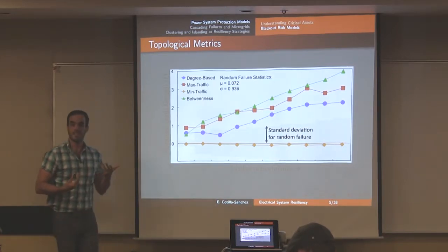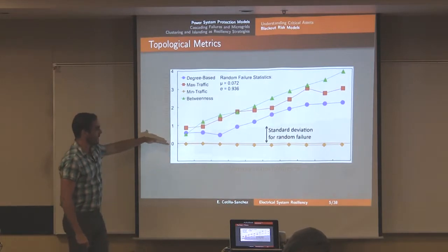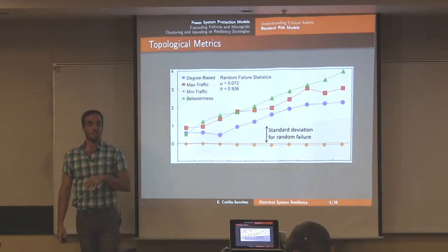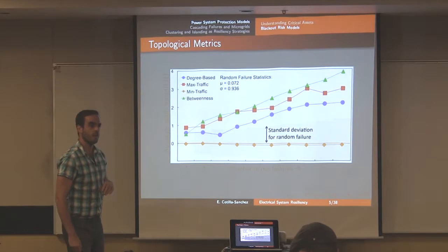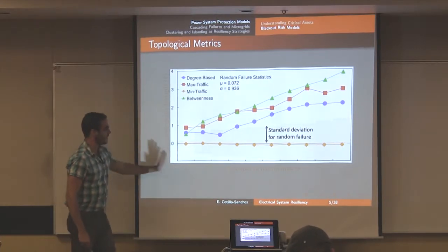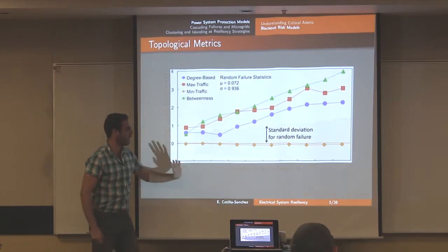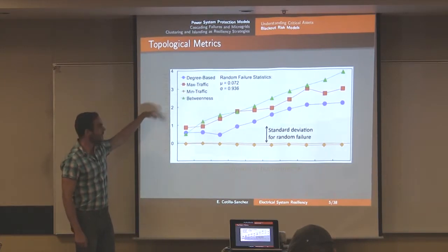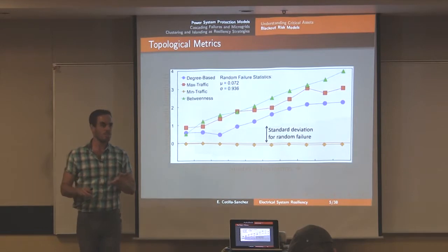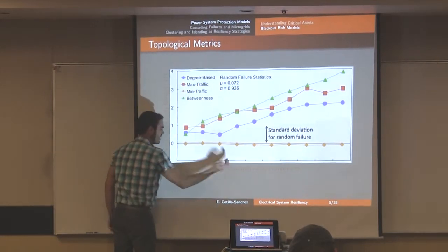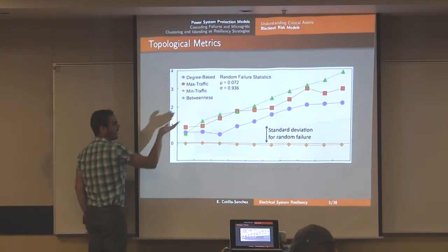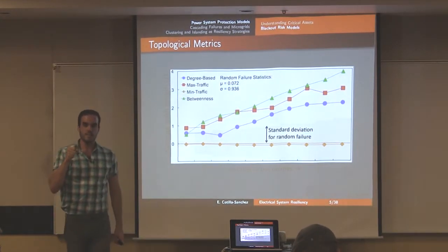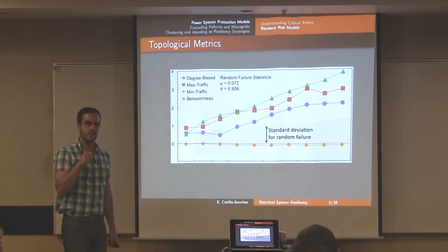So if we look at damage in that way, I just have here a y-axis. This is actually a simulation done with the Eastern Interconnection, so 65,000 buses, the whole East Coast. And I'm looking here at impact. Sorry about the axis, but here in the x-axis is basically how many hits I'm taking to the network, and here I'm measuring the impact on that network. Looking at that topology measure, if I hit one substation, two substations, three substations, the best strategy that I can have is actually to look at betweenness. So I need to hit the substations that are very central. That kind of makes sense.